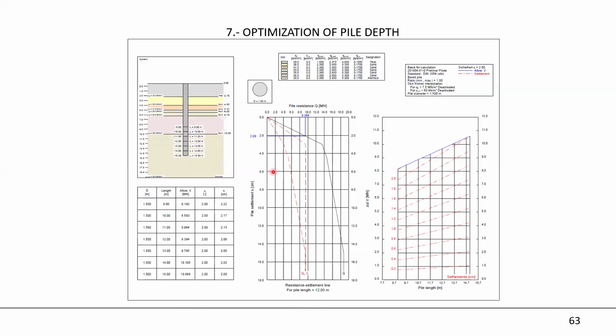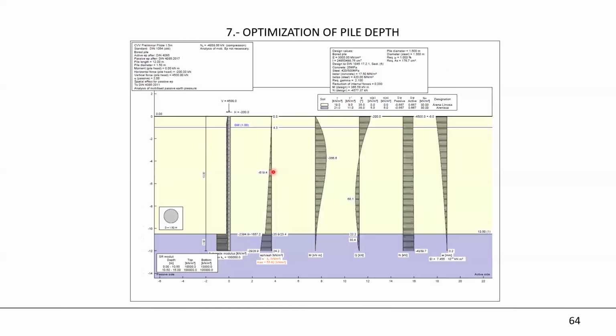And obviously, it's a lot more than the design. And we review the lateral loads too, but it's only an approach. And next, the structural engineer makes the design, but we would like to analyze that to obtain an idea of the load. We make an agreement to introduce the pile socketed in the sandstone, like one diameter, 1.5 meters.